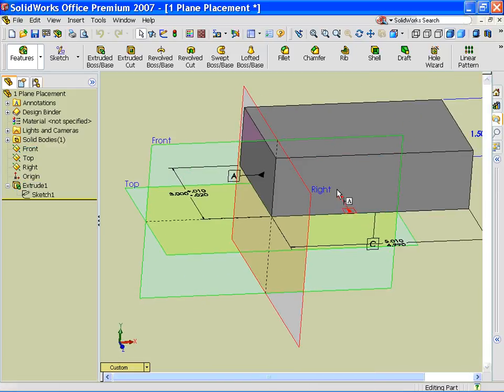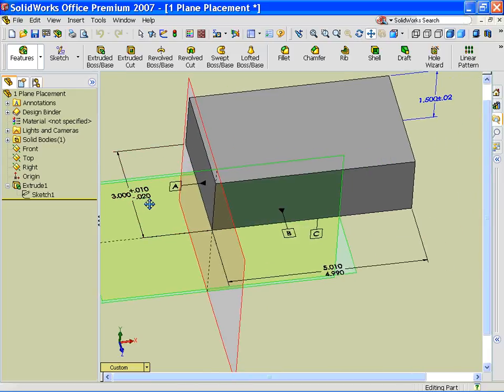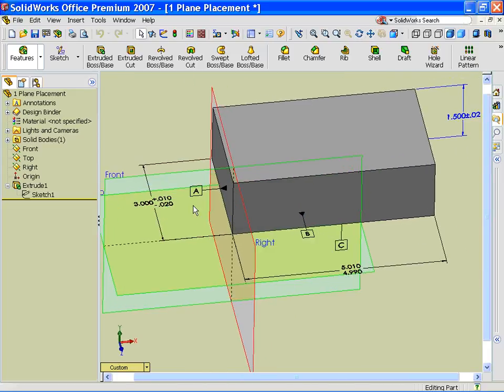As I'm moving this around, you can see there are some annotations on here, things like datums, and I even got dimensions with tolerances. As I made mention about ANSI Y14.41, this enables us to take advantage of our 3D model as a drawing, so that's what this is all just thrown on here for.